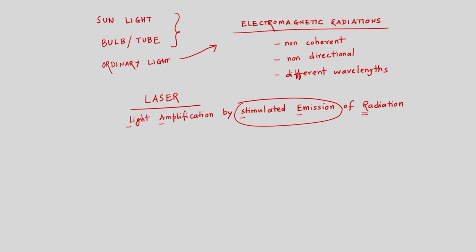So, the high power light is focused on a very small area, a very small diameter beam, and due to that the power density is increased, and due to that high power density we can carry out the intended operation, say melting operation or vaporization operation, or even forming operation, just heating operation.